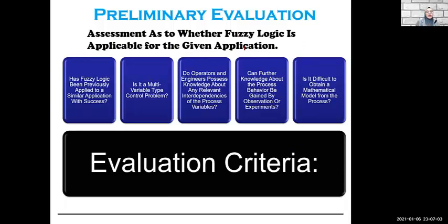So this is an assessment as to whether fuzzy logic is applicable for the given application. So you need to evaluate. These are the evaluation criteria. Has fuzzy logic been previously applied to a similar application with success? Is it a multi-variable type control problem? Do operators and engineers possess knowledge about any relevant interdependencies of the process variables?